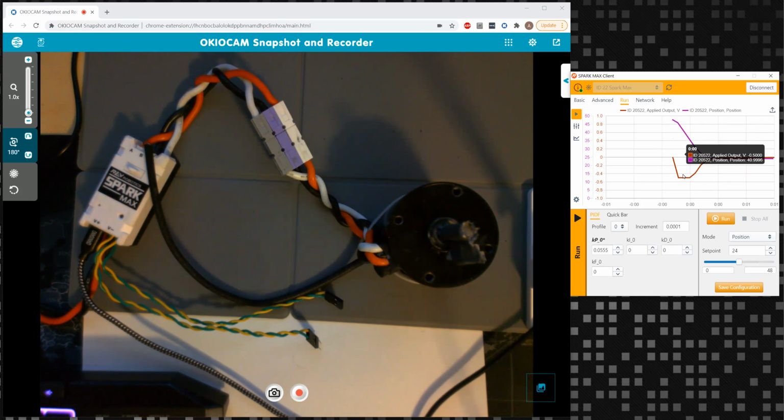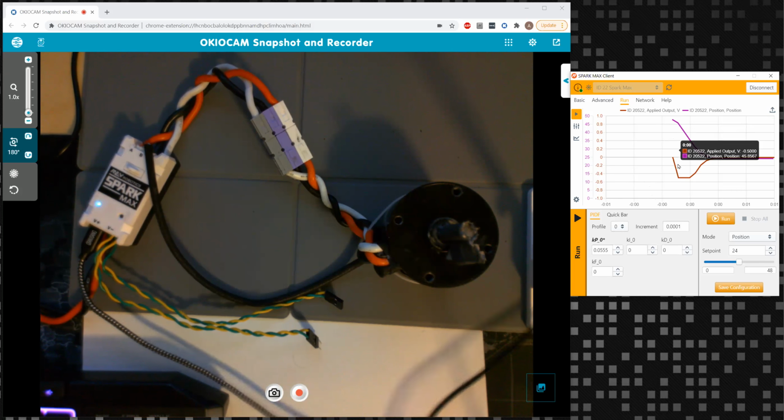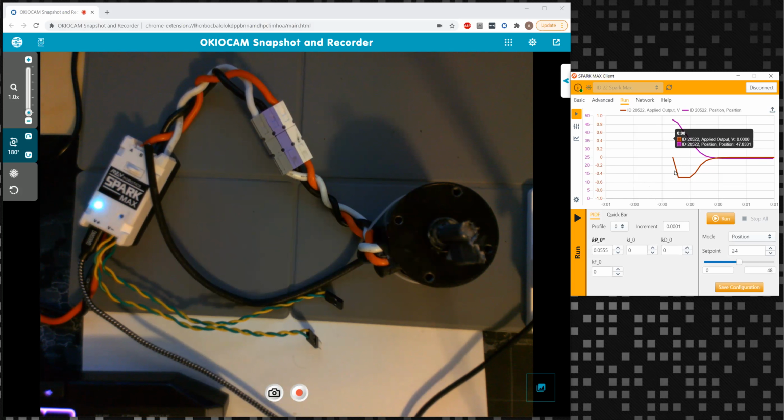And it was doing all of that negative because it was going backwards, right? And so all of that math still works for us, since if the command point is less than our current measurement, we'll get a negative value. So the motor will output negative, and the equation just sort of works and does what we want it to do.